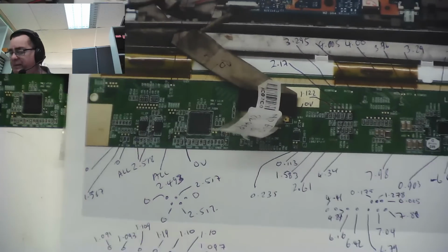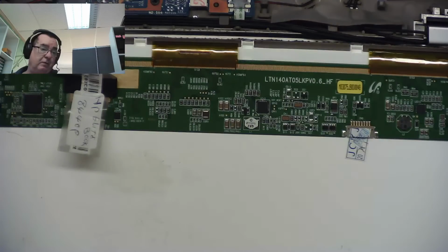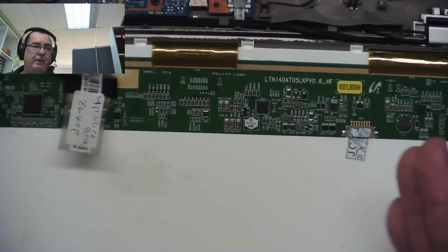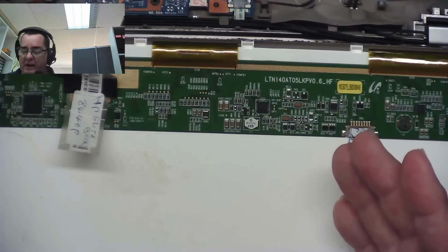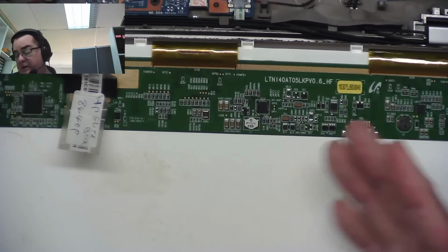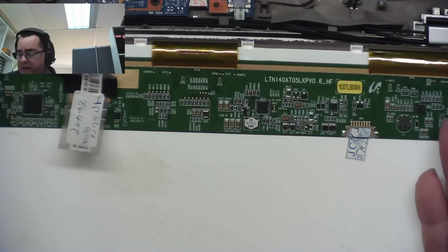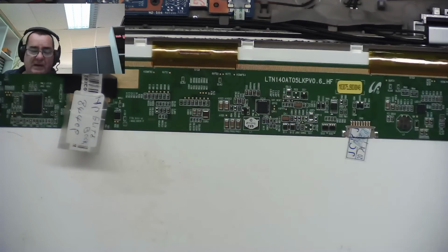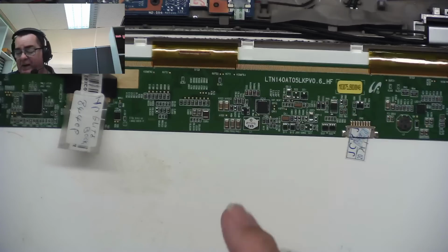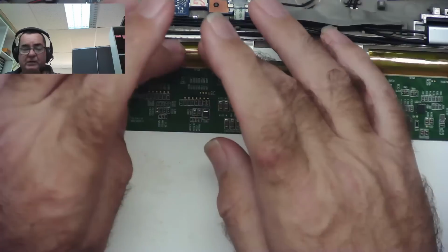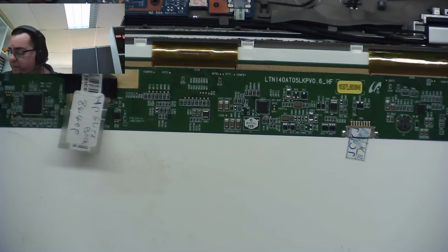So in the meantime, while this guy was telling me about these EPROMs, somebody else on the Bad Caps Forum came back and said, look, Rich, if all the voltages are present for the LCD panel, VGH, VGL, VCOM, blah, blah, then if it still doesn't work and you've got data going to it and it's recognising it, it's the panel itself. There's something wrong with these chips on the flex or something with the panel.